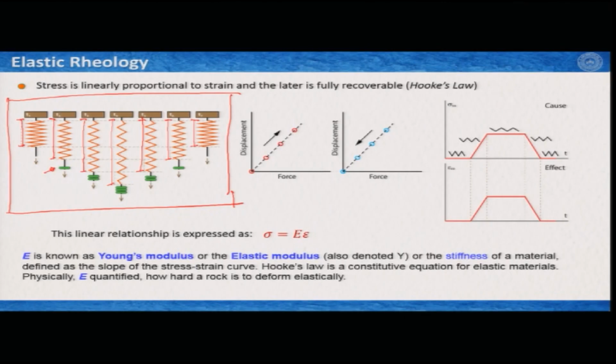So, if I now plot them in a displacement versus force curve, then with the application of force, with the 3 different loads I have, when we are loading it, we get some points, and if I connect these points, they generally fall in a linear pattern. And when I release these loads, they also come back in a very similar fashion and also maintain a linear relationship.